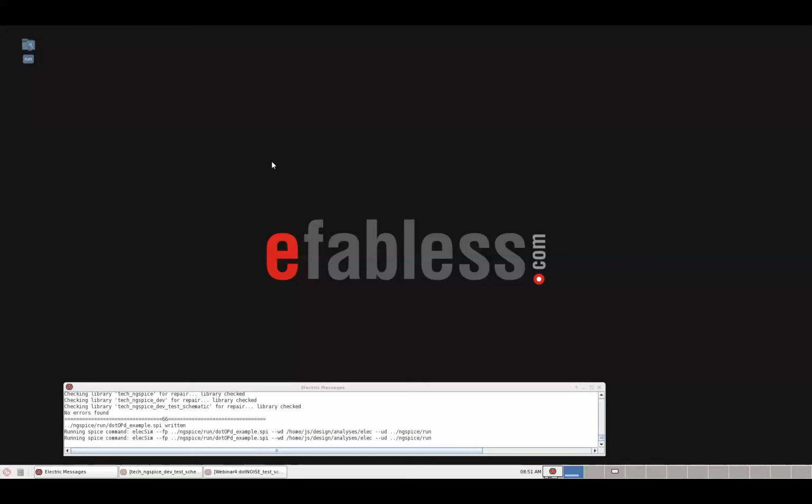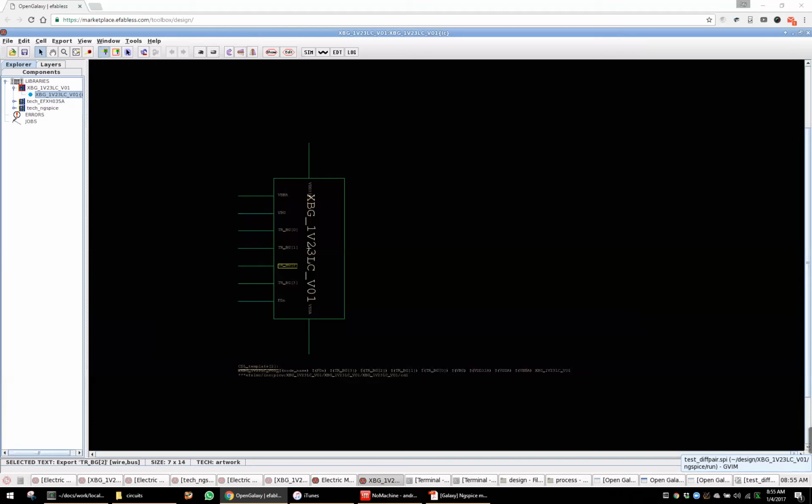Yeah, the minimum widths are DRC specific widths or lengths that are defined. Although the models support going as low as 0.45, and I've seen 0.3 works pretty much all right, as far as layouts are concerned, like you said, it might be an amazing design on schematic models, but when it comes to layouts and DRC, it's going to completely violate that 0.4, 0.45. Yeah, I agree with that.